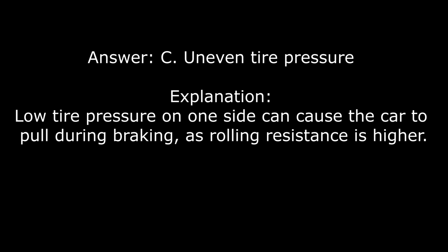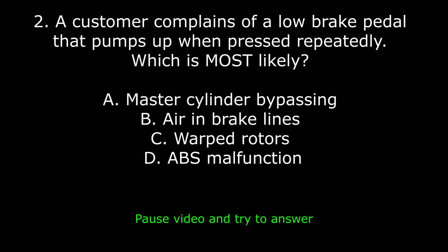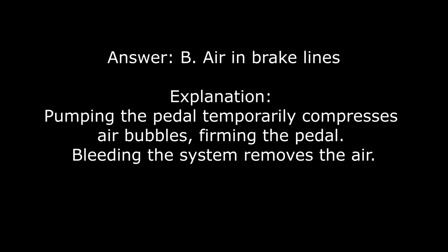2. A customer complains of a low brake pedal that pumps up when pressed repeatedly. Which is most likely? A. Master cylinder bypassing. B. Air in brake lines. C. Warped rotors. D. ABS malfunction. Answer: B. Air in brake lines. Explanation: pumping the pedal temporarily compresses air bubbles, firming the pedal. Bleeding the system removes the air.